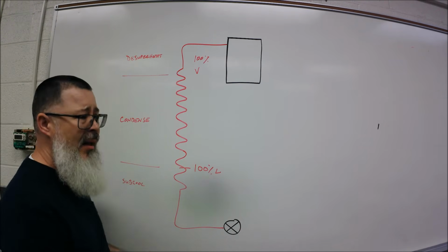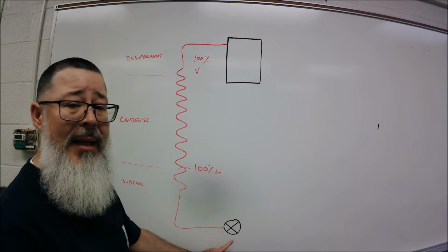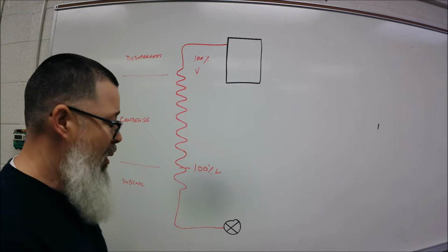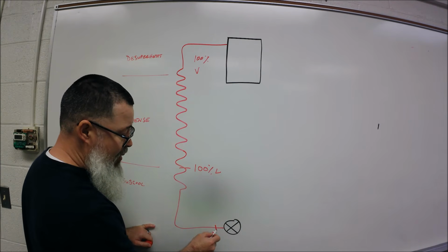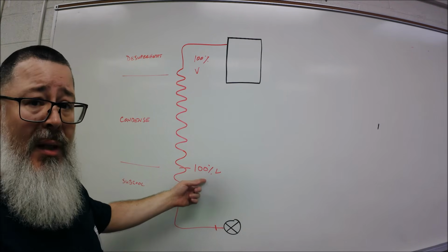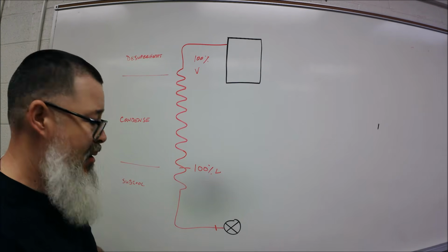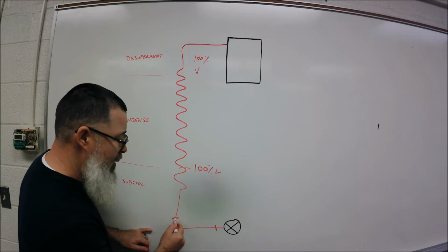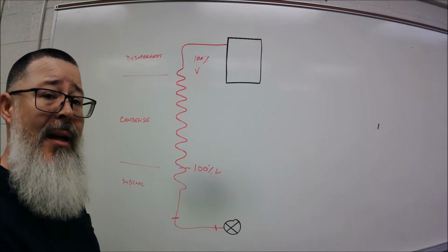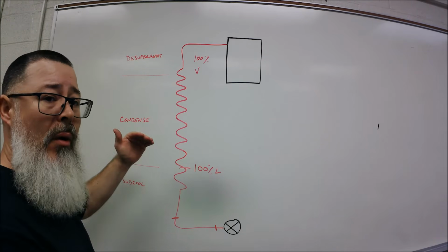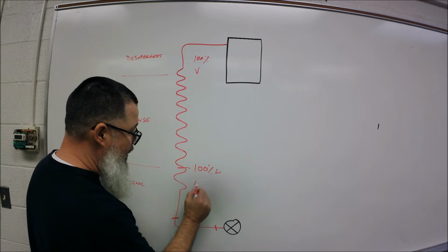So just to give you an idea of how I think about subcooling, it's very much like superheat. I know where it ends. So the closer to it, I might have 1 degree of subcooling. Oh, then my 100% liquid point happened very close to my metering device. 5 degrees of subcooling. Oh, well then that happened a little further back. I've got a little more liquid in the line. It happened a little further back towards the coil. Oh, I've got 10 degrees of subcooling, right there.